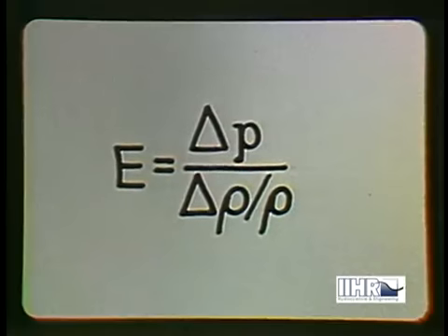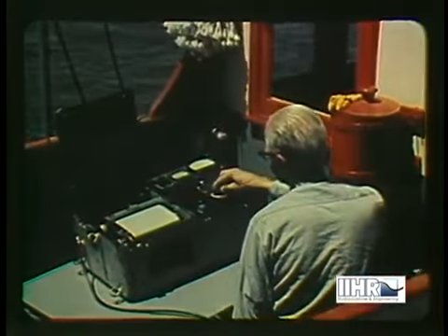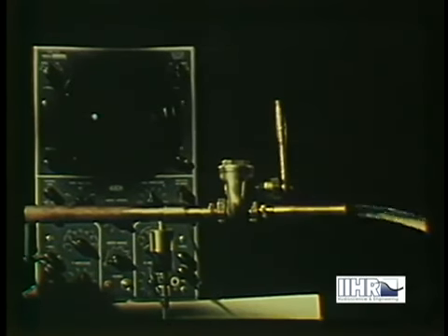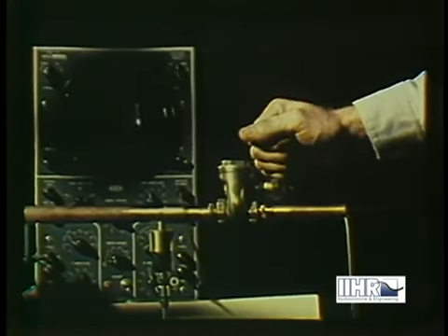Another fluid property of importance is elasticity, the ratio of applied pressure to the relative change in density that it produces. Though usually considered incompressible, liquids are sufficiently elastic to permit submarine signaling and sounding by the generation and reflection of elastic waves, as in this Corps of Engineers Mississippi River measurement of channel topography. When a valve is suddenly closed, elastic waves also cause the noisy plumbing phenomenon known as water hammer.